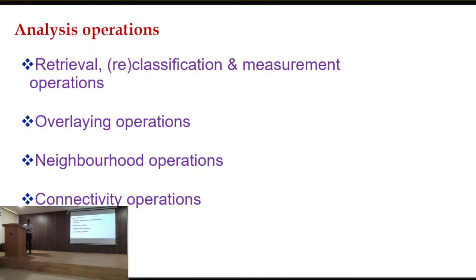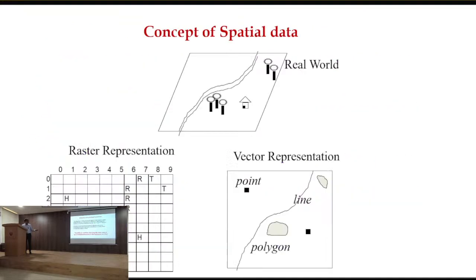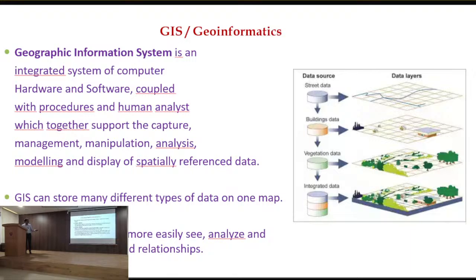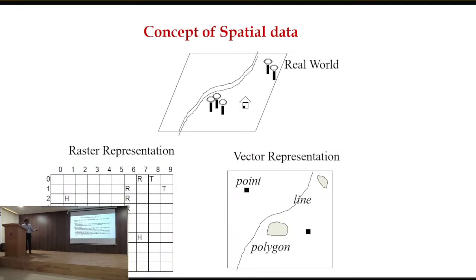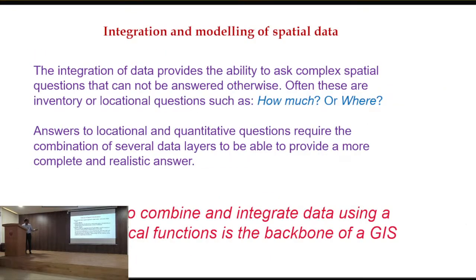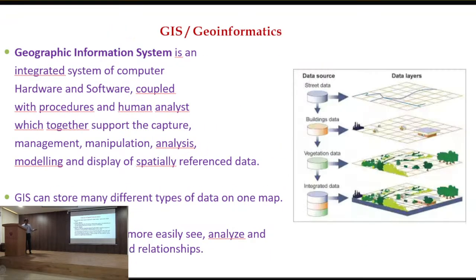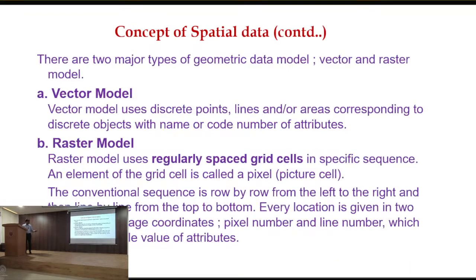Okay, can I consider it as continuous, in the sense I can go for raster if it is continuous and vector if it is discrete? That is what the definition itself says. I have written here: vector model uses discrete points. For discrete analysis, this model is better. For continuous and faster analysis, suppose you have acquired your satellite data today and immediately you want to produce results on the same day with minimum information, raster is more suitable.